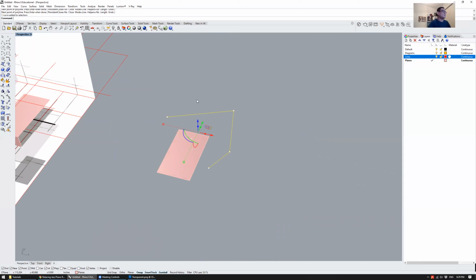This is what we call a polyline. It's a line that is joined together with several segments in it. Generally you will be drawing with polylines as opposed to individual lines, but for now, we're just going to stick with this. Change it to the line layer, copy object to layer. Okay, so this is red. There's a second curve. Sorry, I should have done change object layer.